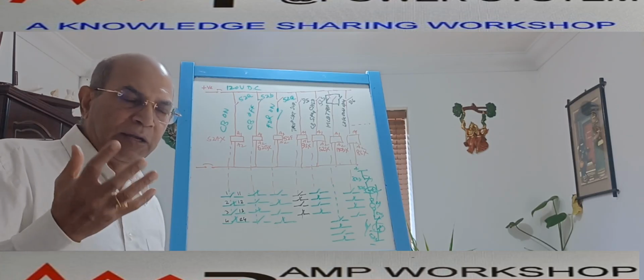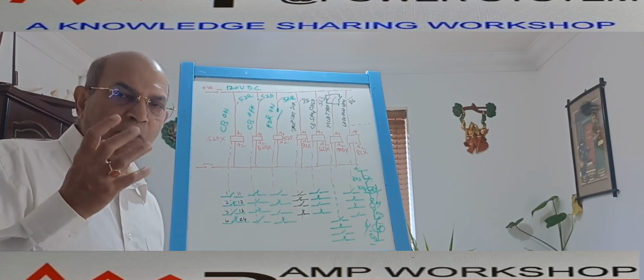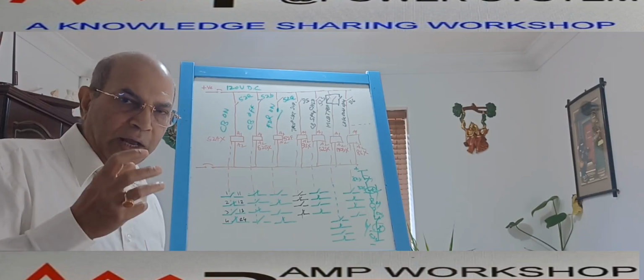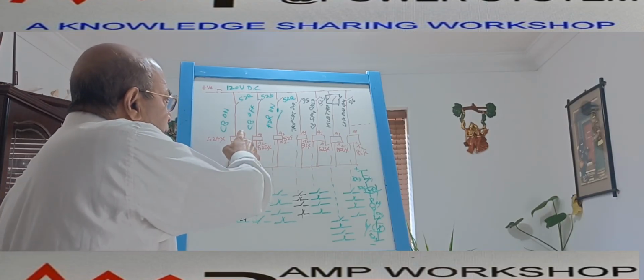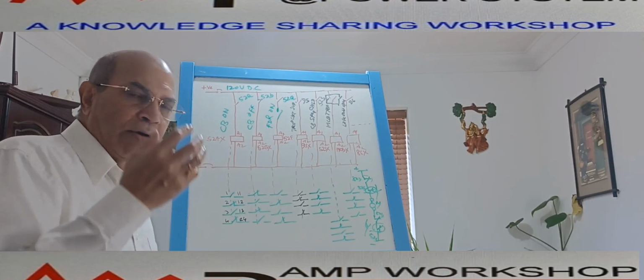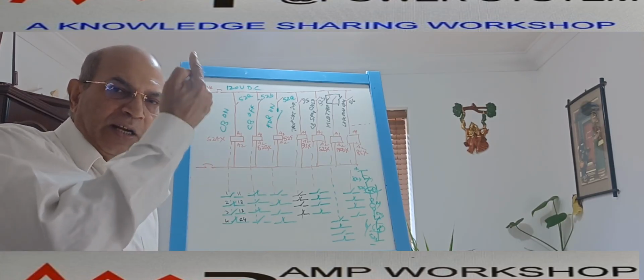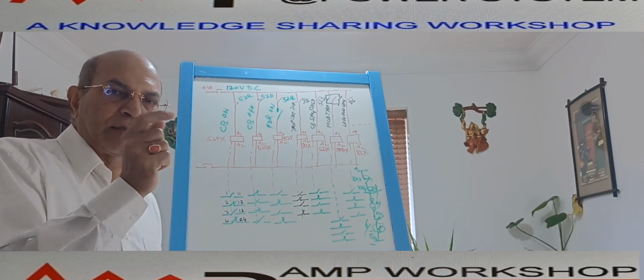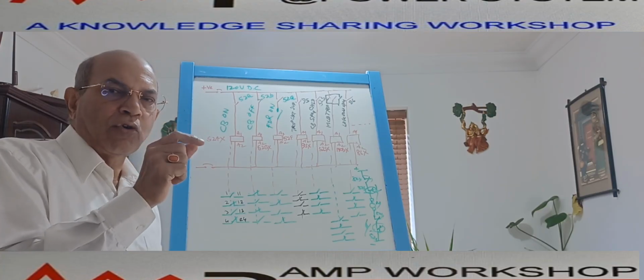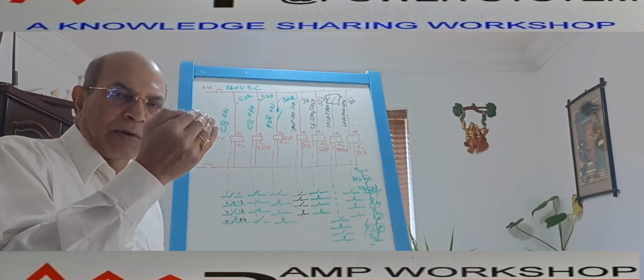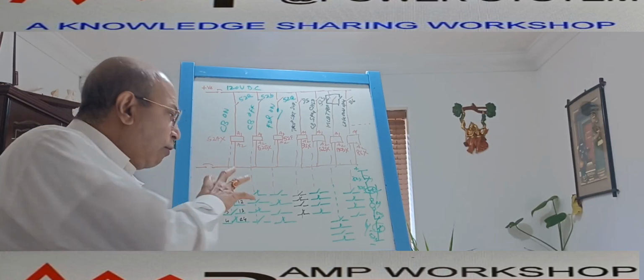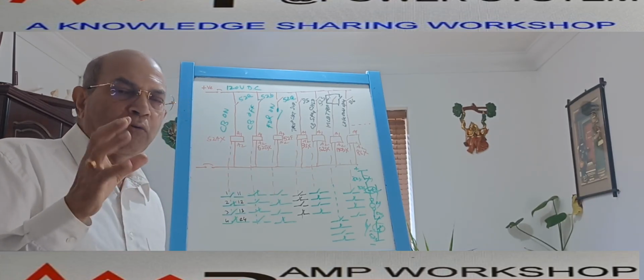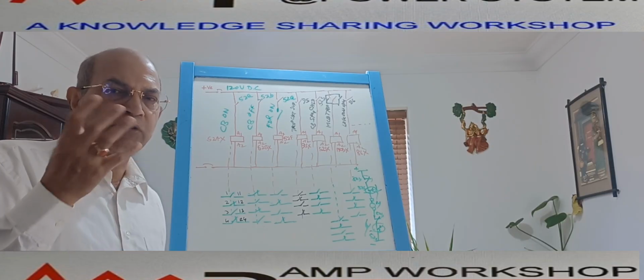And these auxiliary relays are all small electromagnetic relays. This relay has a coil, which we normally show as A1, A2. When the coil gets energized, there is a spindle, and on the spindle there are various contacts. All the auxiliary contacts are shown when the coil is not energized, that means the auxiliary relay is not energized.